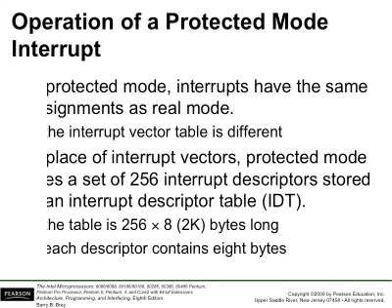If you took Microprocessor 1, you probably remember GDT, IDT, those descriptor tables. And IDT is the one we use to store the interrupt descriptors. Interrupt descriptors tell you the exact location of the interrupt service routine, although we need to do another level of indexing to get the actual address.